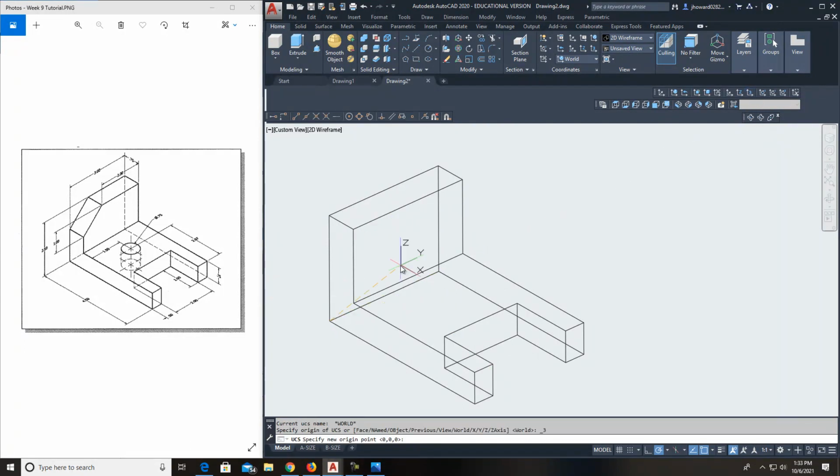So you come to 3-point, click here, click here, click here. There's your XY. Up, 3-point. You've got to click it 3 times. That's why it's called 3-point. That makes your X the first 2 points, and then Y is your next one. And it sets my XY up.